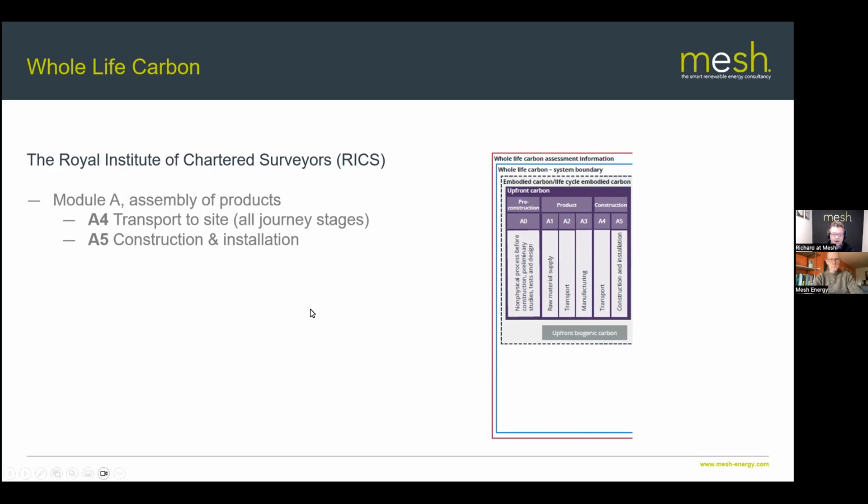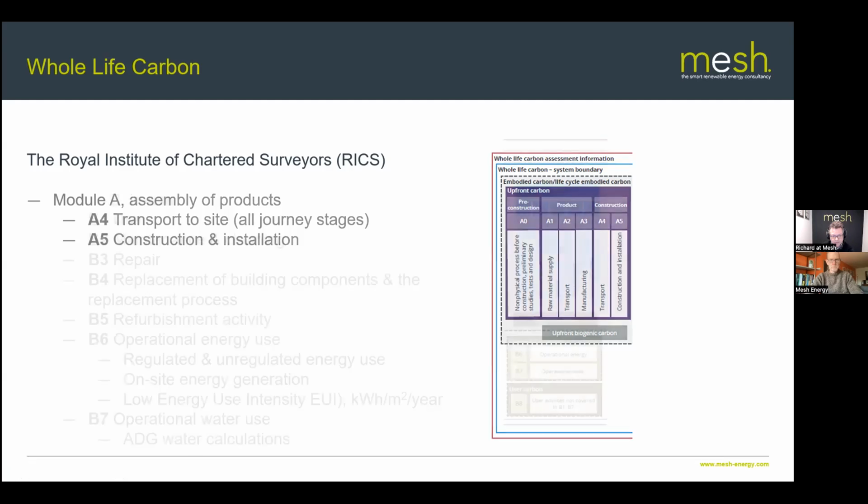And then we allow for construction and installation of the building and the carbon emissions associated with that. Something you can do at stage 5, certainly as part of BREEAM, is that the principal contractor could record their in-construction carbon emissions, and that can be reported back as part of the end of module A. So everything's up for grabs, really.